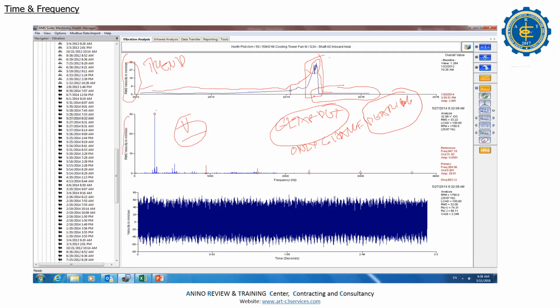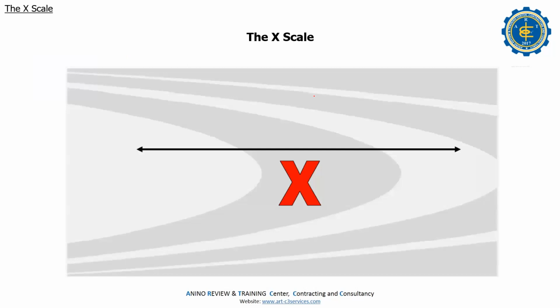So that's another piece of knowledge: when there are abnormal sounds in the gearbox, you should not immediately say change the gear, because the gearbox will make abnormal sounds if the bearing fails.